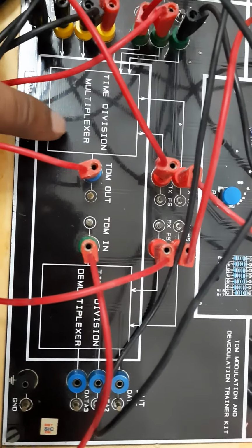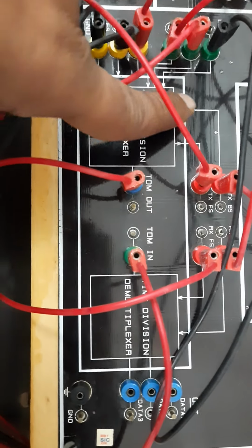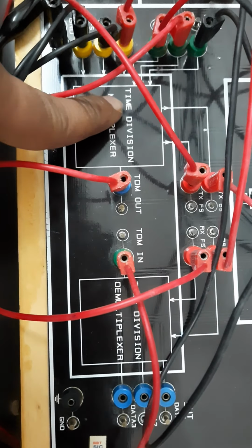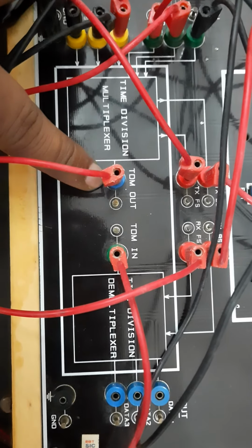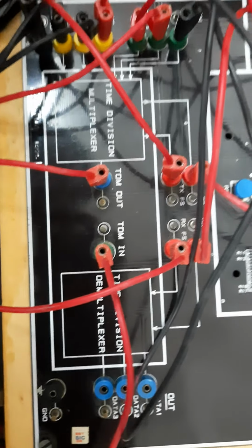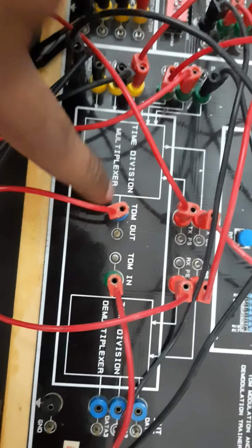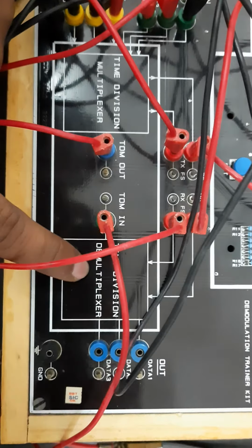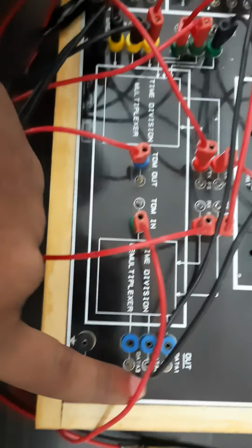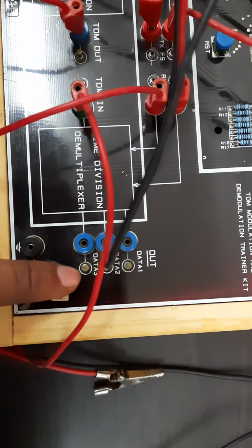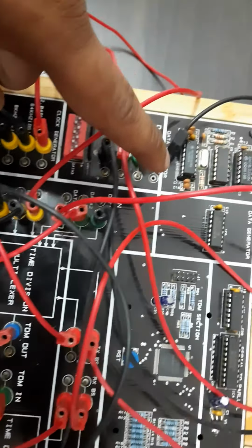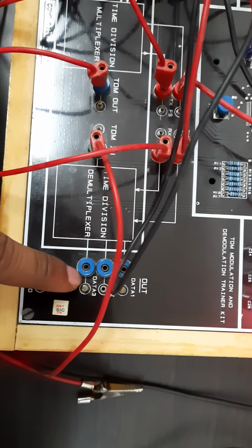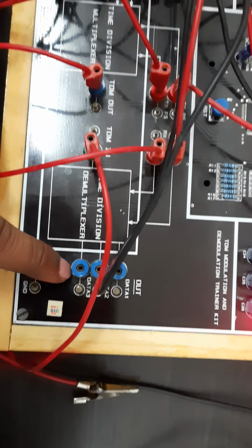Frequency synchronization. You can observe here it is a time division multiplexer. Whatever data we have given here, data 1, data 2, data 3 will come here. Then at this point the TDM output will come, which consists of all three inputs, data 1, data 2, data 3 at a particular time slot. This TDM output is given as the input to the TDM demultiplexer. So at the end again we have data 1, data 2, data 3, whatever information we sent at the transmitter side, the same information will be available at the end. This we need to cross verify using the waveforms on the CRO.